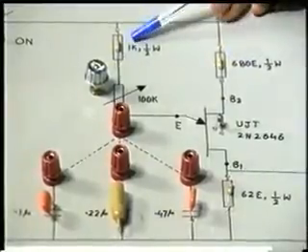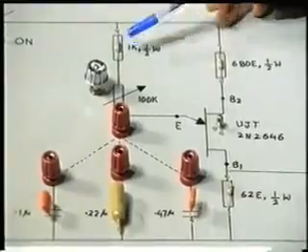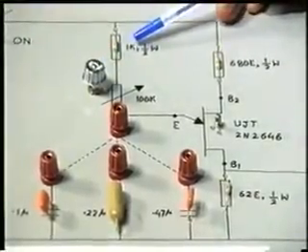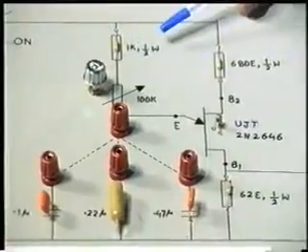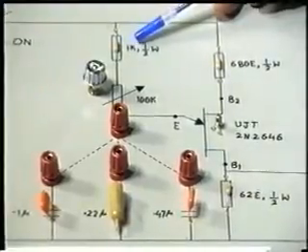Now there is another resistor here which is 1K half watt, this is being used in series with this potentiometer. As a thumb rule we have used it because whenever you are using a resistor or a variable resistor, you must have one resistor in series with it.